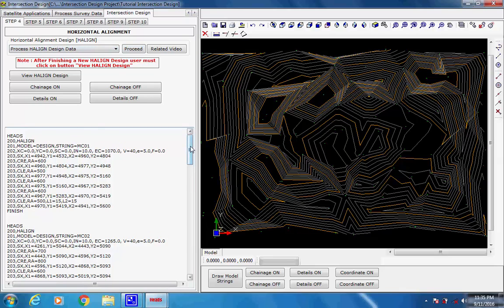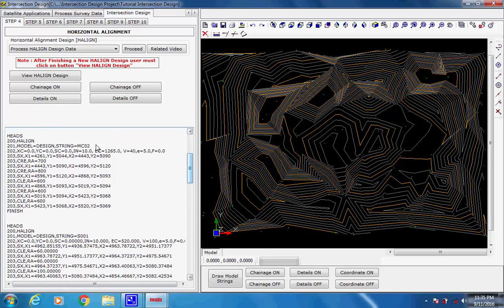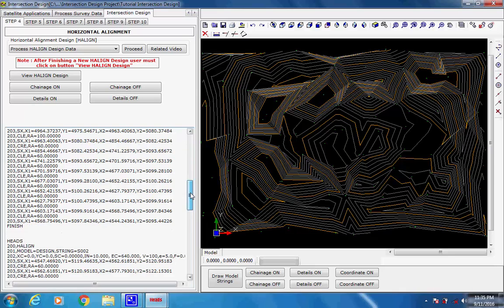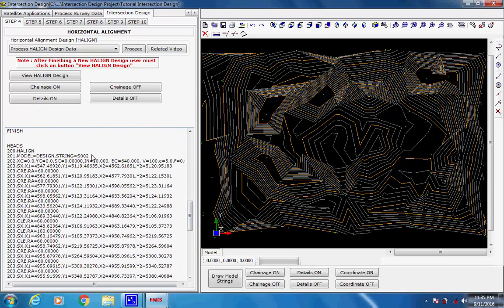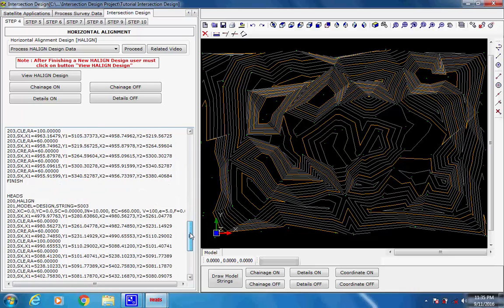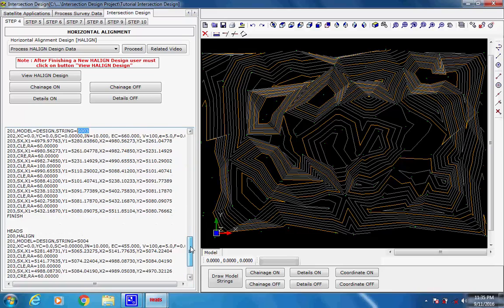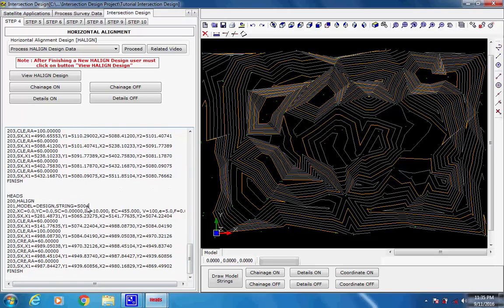These are for the design of horizontal alignments for two main intersecting crossroads MC01 and MC02 and 4 slip roads S001, S002, S003 and S004 connecting the two main crossroads. In other design work there may be some more or less number of alignments.